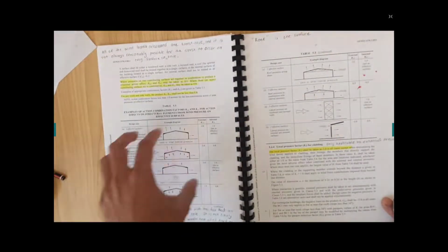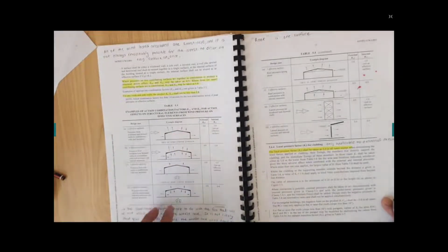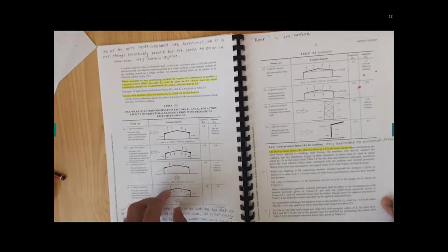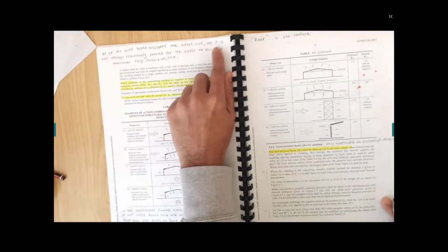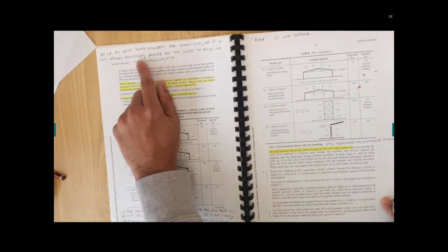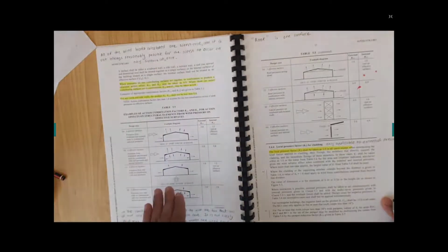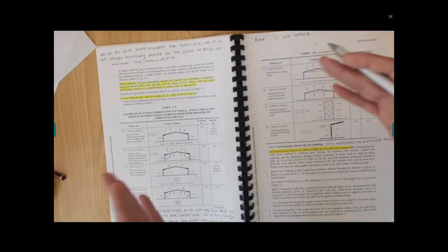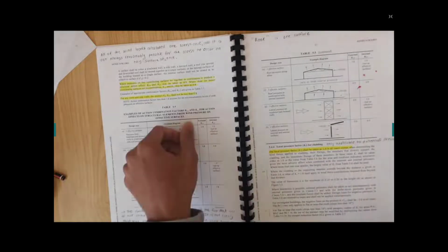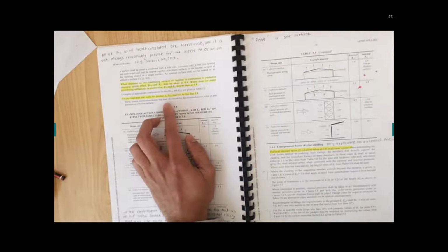Basically I explained to you this Kc. Kc is a combination factor. When the wind hits the surface, you will not have the worst case for everything. All the winds calculated are worst case, and it is not always possible for the worst to occur on every surface at once. So if the wind hits the windward wall, your side walls and roof are not worst case, only the windward wall is worst case. So you can combine and reduce those pressures. But the catch here is, you can't reduce that value so fast.